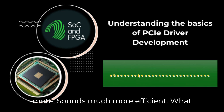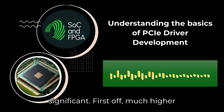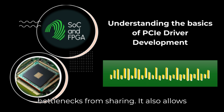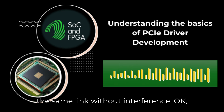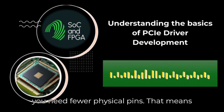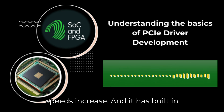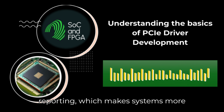Sounds much more efficient. What are the key benefits of that? Oh, they're significant. First off, much higher throughput. Way more data can move. Because it's dedicated. Right, no bottlenecks from sharing. It also allows for full duplex communication, data sending and receiving at the same time on the same link without interference. And because it's serial, not parallel, you need fewer physical pins. That means smaller connectors, smaller footprints on the board. Plus, it scales much better as speeds increase, and it has built-in error detection, AER, advanced error reporting, which makes systems more reliable.